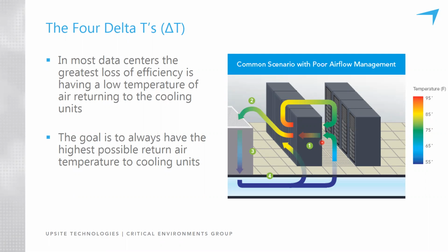So why are these 2 locations having significant temperature changes when there's no heat source or nothing to cool the air? Well, the obvious answer is that when exhaust air leaves the IT equipment on its way back to the cooling units, extra cold air has mixed in and reduced that air temperature.